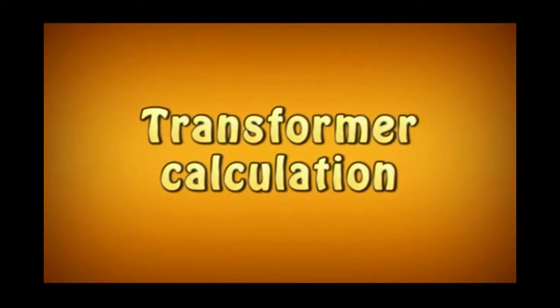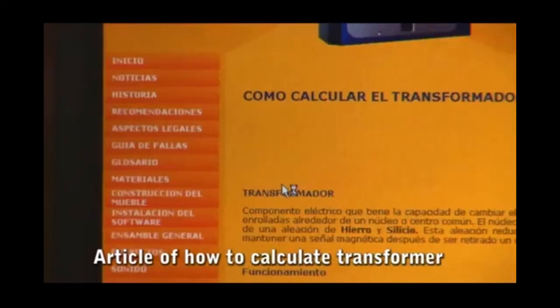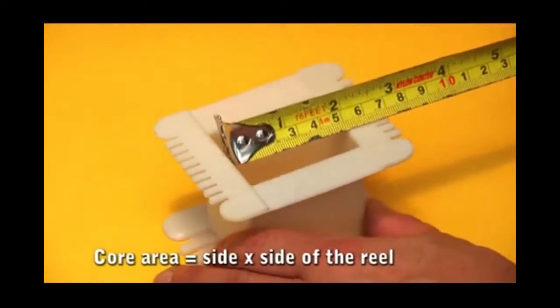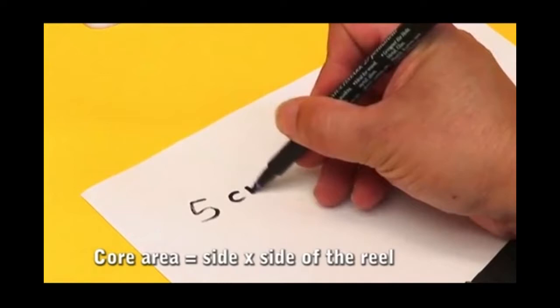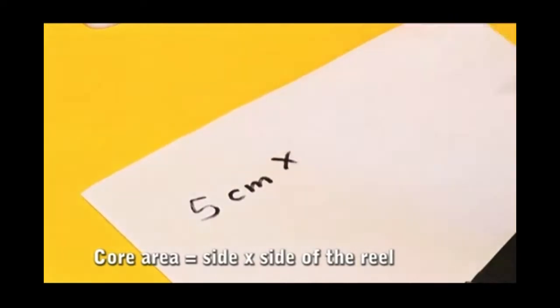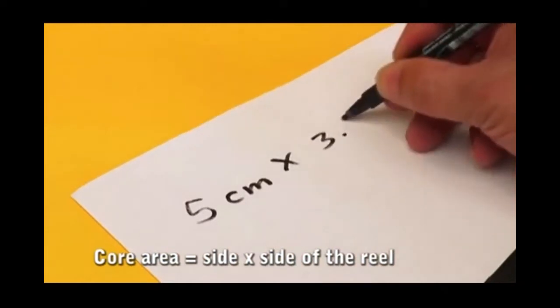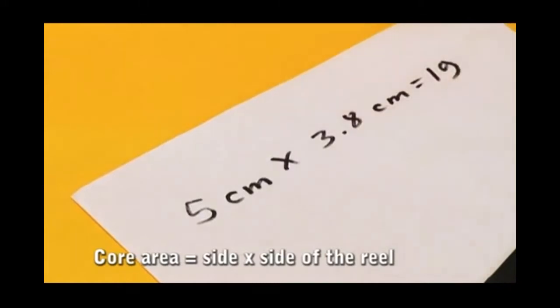Calculation of transformers. Before the construction of a transformer, you should study our article on how to calculate a transformer. To calculate the number of turns of wire, we take the core area as the product of multiplying side by side of the mold. In this case, we have a formwork of 5 by 3.8 centimeters, which gives us a core with an area of 19 square centimeters.